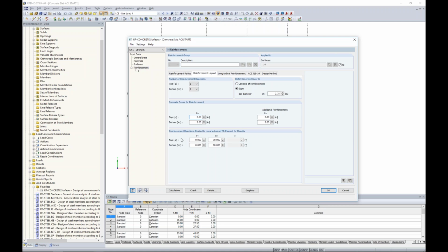Something interesting here, we have the angle set at 0 and 90 degrees. So we have 2 different reinforcement directions, and right now they're set 90 degrees apart from each other. But you have all the control in the world to change this if you'd like. Not everything is as simple as we want, especially with more complex designs these days. So maybe you have a load distribution type that calls for something more like 45 degrees for your second reinforcement direction.